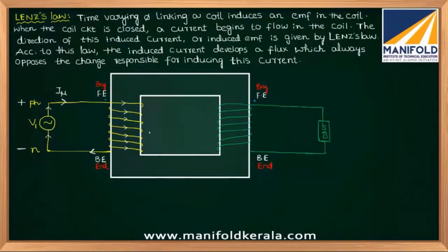Yes, very good. So guys, now please apply the right hand thumb rule, which I explained. I think you remember image 1, image 2. In this case, you have to use image number 1 or image number 2? Image 1, very good. Suppose I hold the core like image number 1, what might be the direction of flux?